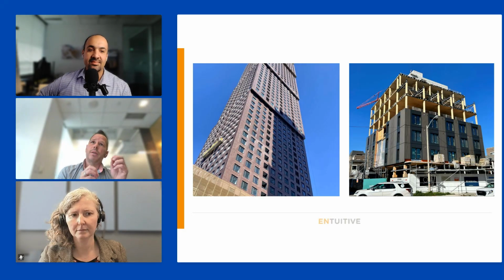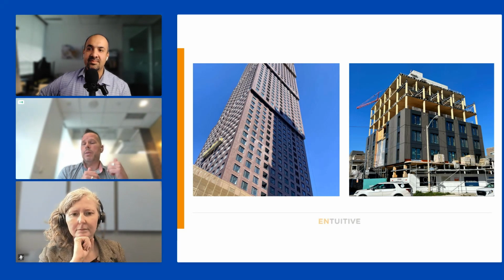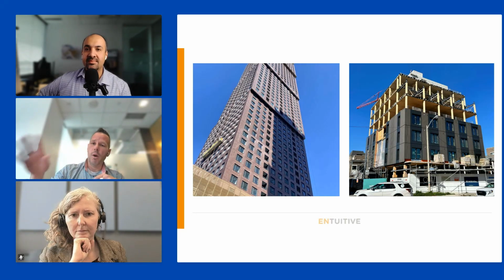So I mentioned that I wanted to talk about window perimeter. The other cool thing with thermal bridging is if you put in a better window, the transmittance at the perimeter of the window also comes down. So it's not just a matter of saying, well, can we just downgrade the window? Yes, sure. Maybe in the energy model, if you're just thinking about window performance, that may be okay if you have room in your energy performance to downgrade to a double glaze, for example. But that will increase the transmittance at the window perimeter, which will further downgrade your wall performance. So these are real knock-on interplays that you have to be very mindful of.